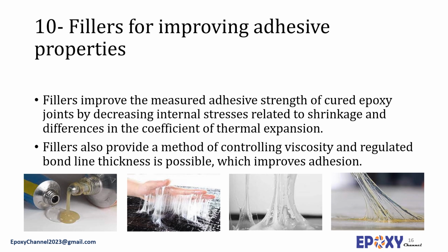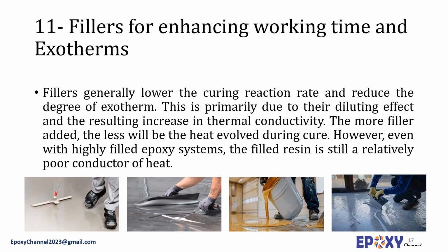epoxy adhesive systems. Fillers generally lower the curing reaction rate and reduce the degree of exotherm. This is primarily due to their bulk diluting effect and the resulting increase in thermal conductivity. The more filler added, the less will be the heat evolved during cure. However, even with a highly filled epoxy system, the filled resin is still a relatively poor conductor of heat.